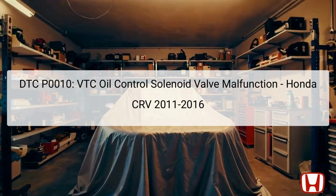The DTC P0010 indicates a malfunction within the variable timing control (VTC) oil control solenoid valve in the Honda CRV models from 2011 to 2016. This issue typically arises when the solenoid valve fails to regulate oil flow properly, affecting the timing of the engine's valve system.